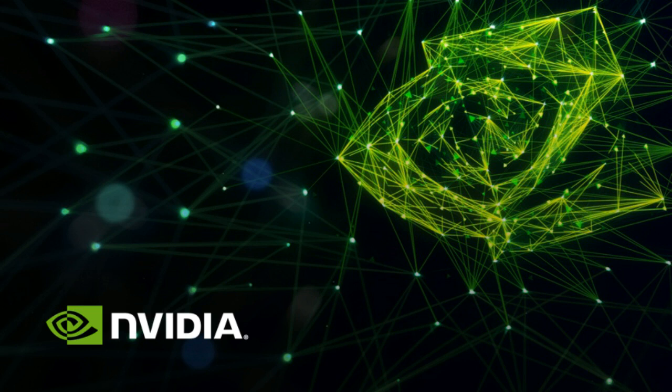Actually, they have a couple stereo cameras. One's a USB 3, and they also have a MIPI CSI stereo camera that work well. And then there's also a vendor, Duo3D. They have stereo cameras that support CUDA as well. So the main part is to find stereo cameras that support CUDA for doing all of the stereo disparity mapping and such, because you don't want that done on the CPU.